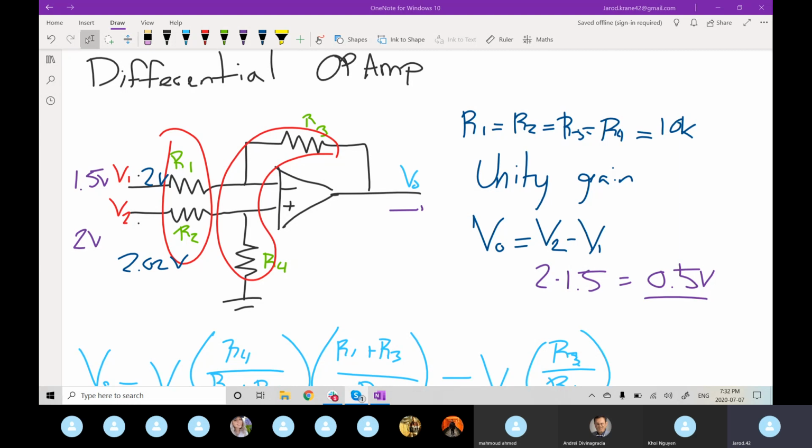So if you want to still translate a 1 volt change on the high voltage side, which will only be millivolts on the low voltage side, you would use something like this so that you can amplify that signal back up into a readable, distinguishable voltage range.